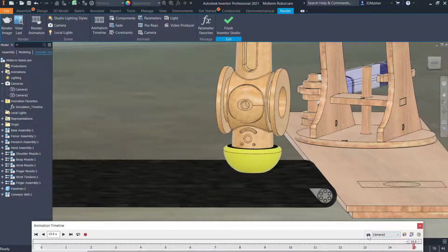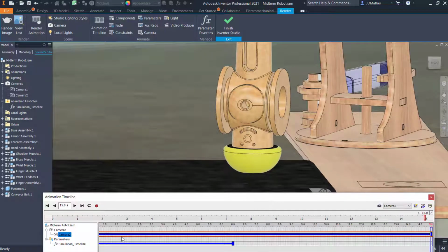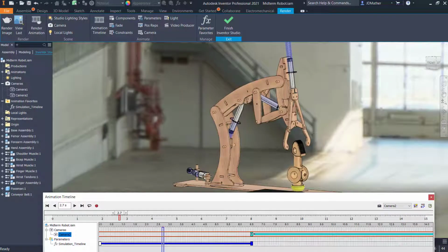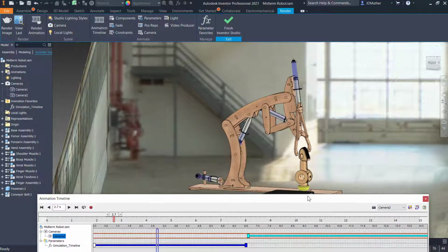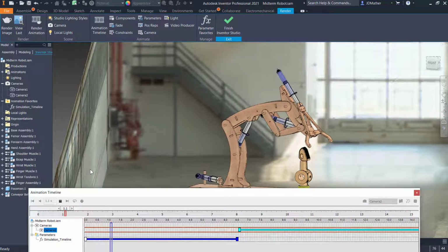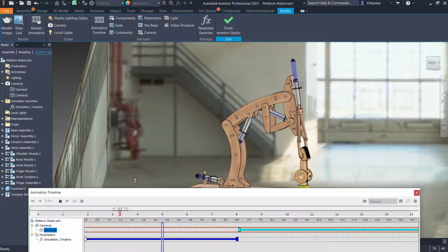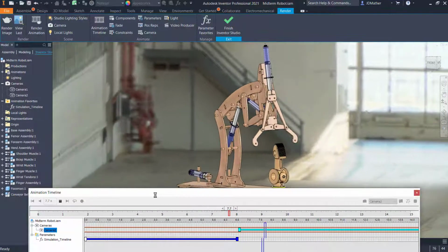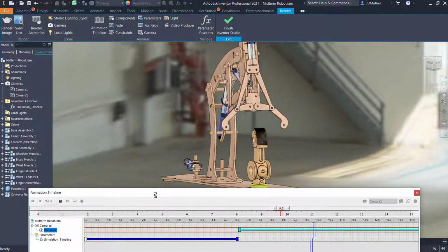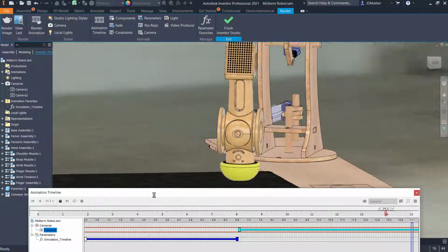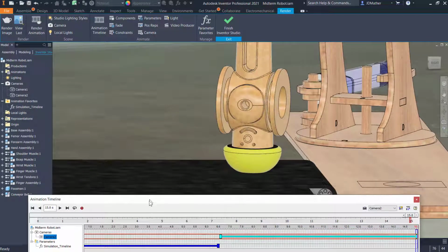will add a camera action for that zoom, and I'm going to then put that zoom period to occur from 6.5 seconds to maybe the 15 seconds. And so if I play this, we'll see it do the pickup, it'll go over, and then it'll zoom in on that location. And maybe while it's zooming in on that location, I want to repeat this operation.